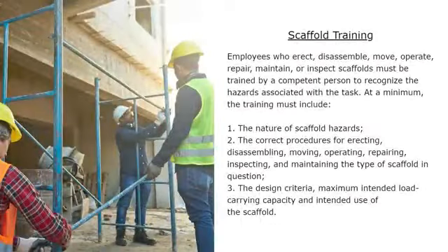Scaffold training. Employees who erect, disassemble, move, operate, repair, maintain, or inspect scaffolds must be trained by a competent person to recognize hazards associated with the task. At a minimum, this training must include: Number 1, the nature of scaffold hazards. Number 2, the correct procedures for erecting, disassembling, moving, operating, repairing, inspecting, and maintaining the type of scaffold in question. Number 3, the design criteria, maximum intended load carrying capacity and intended use of the scaffold.